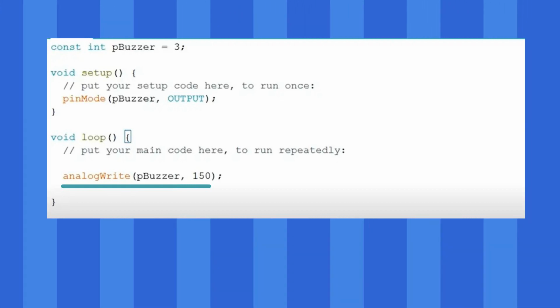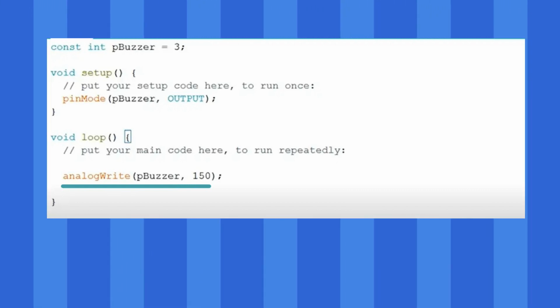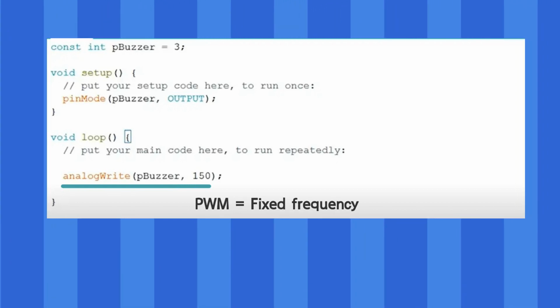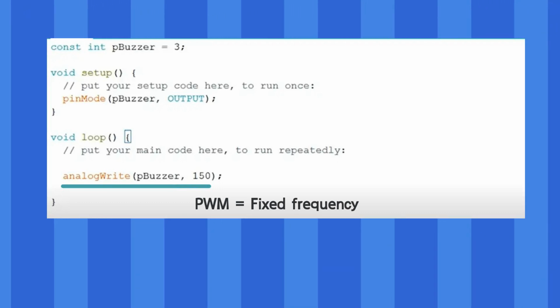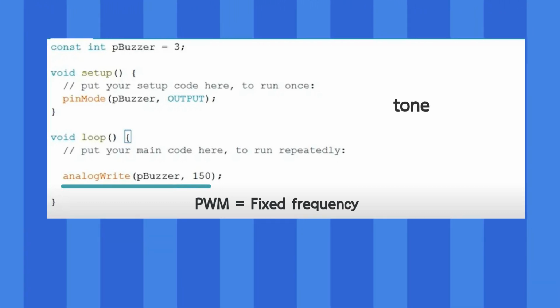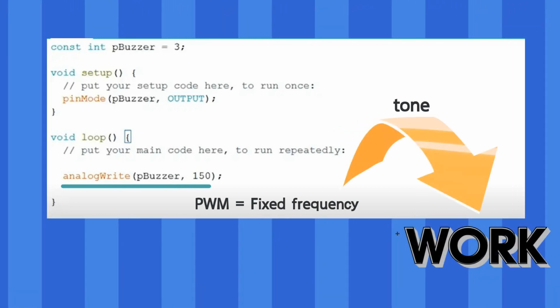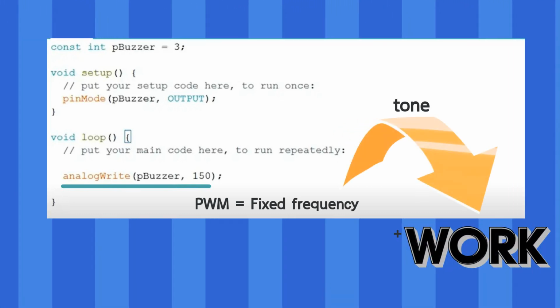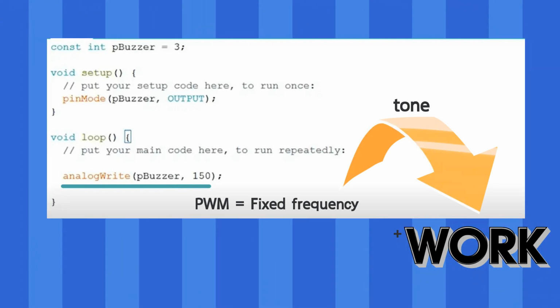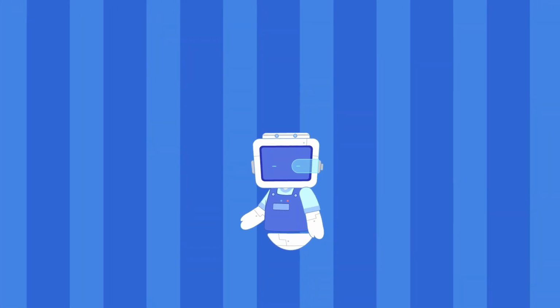It's important to note that the PWM pin has a fixed frequency. If we want to change the frequency, we can use the tone function, but this would create a problem with other applications that need to use the time or delay. To make programming a melody easier, we will use a library and other programming methods for passive buzzer in the next video tutorial. We will learn to make projects with the active and passive buzzer.